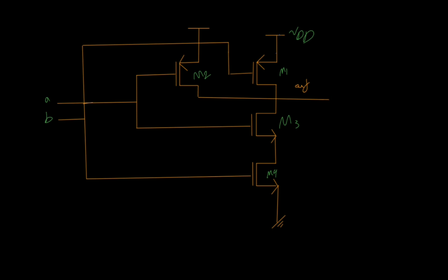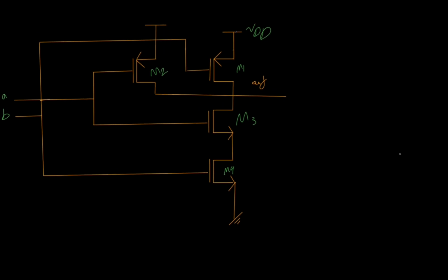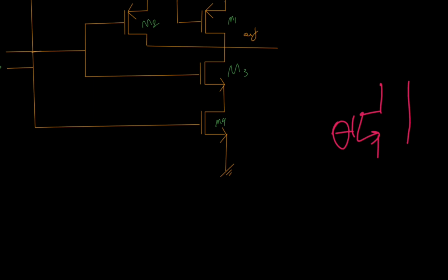So we talked before that we have two kinds of transistors or MOSFETs, NMOS and PMOS. As a brief overview, an NMOS would be on if we apply 1 or high voltage at the gate, and in that mode the transistor would act as a short circuit or a resistor. And if we have zero, obviously it would act as an open circuit. And if it is a PMOS, then the opposite of this would happen.